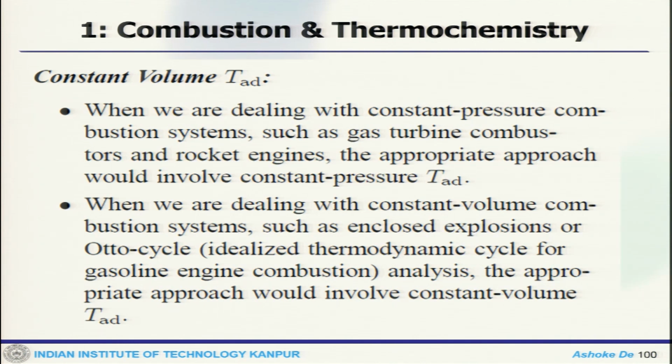Now, the second one is the constant volume adiabatic temperature. For a constant pressure combustion system such as a gas turbine or rocket engine, the appropriate approach would involve the constant pressure adiabatic flame temperature. So, depending on the example, one can use a different approach, whether constant pressure or constant volume. When we are dealing with a constant volume combustion system such as an enclosed explosion or Otto cycle analysis, the appropriate approach would involve the constant volume adiabatic flame temperature.